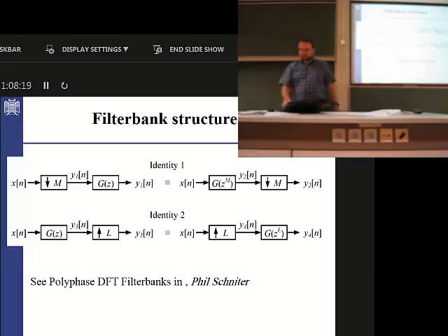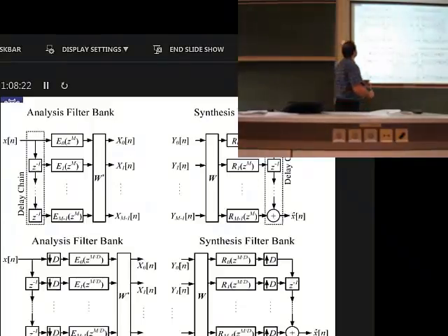So putting all these together means that in the filter bank design, where you have such a structure for the input and the same thing for the output, you know that we have the filter and then the downsampler. You can change the places, and this changing of the places between the downsampler and the filter changes the filter taps like this, which are nothing but the polyphase filters.